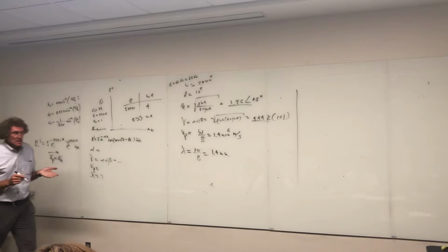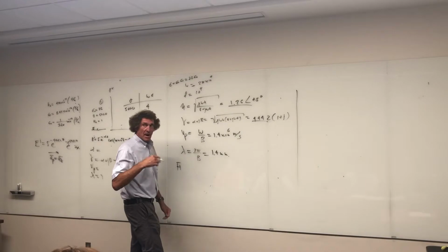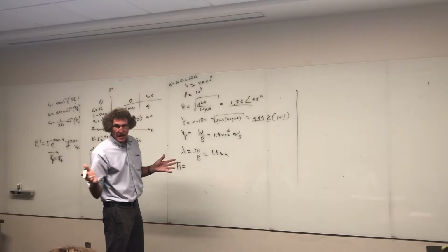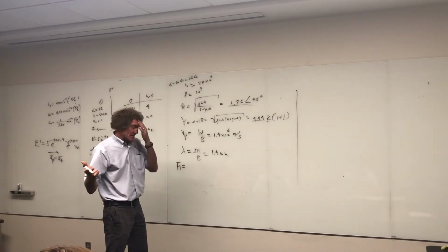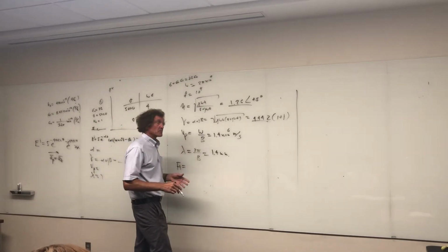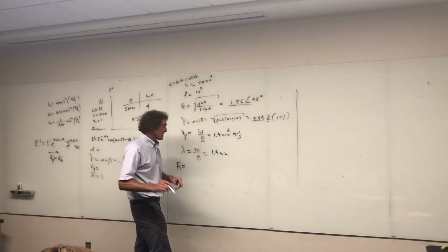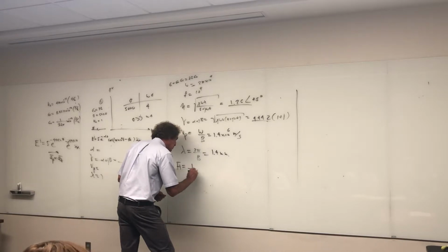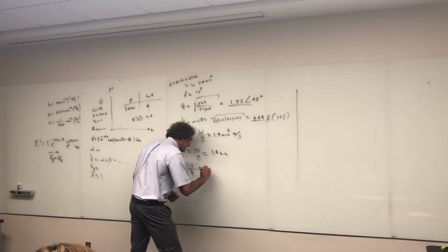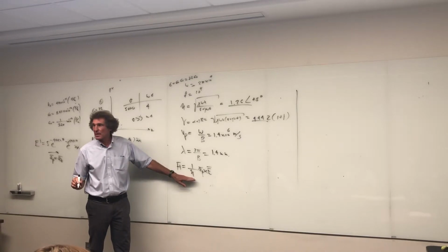Now, once we have that, to get the value of H, I'll use the formula I showed you, the simple one. Instead of having to do the curl of E and then dividing by that constant, sigma plus j omega epsilon, which is a pain, you would have to take the curl of E and divide it by minus j omega mu. Instead of doing that, you can use that little trick I showed you, which is 1 over eta, unit vector in the direction of propagation cross E, because these are propagating waves, so you can do that. You can't use this generally. This is for a propagating wave. Are you with me, class?